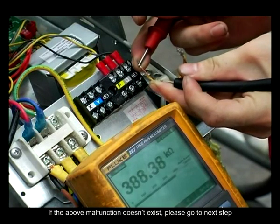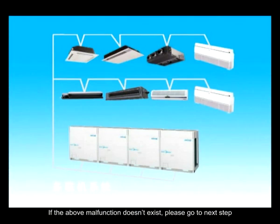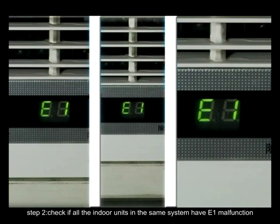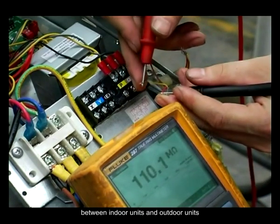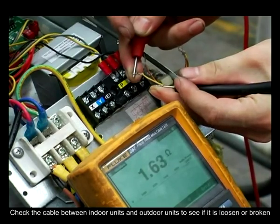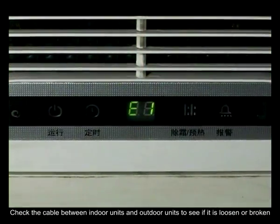If the above malfunction doesn't exist, please go to next step. Step 2. Check if all the indoor units in the same system have E1 malfunction. If so, the malfunction should be caused by the communication cable between indoor units and outdoor units. Check the cable between indoor units and outdoor units to see if it is loosened or broken.